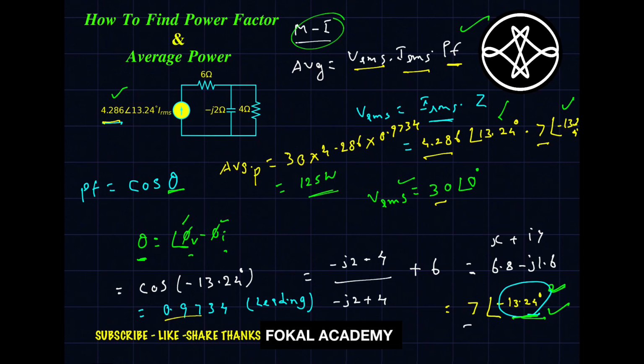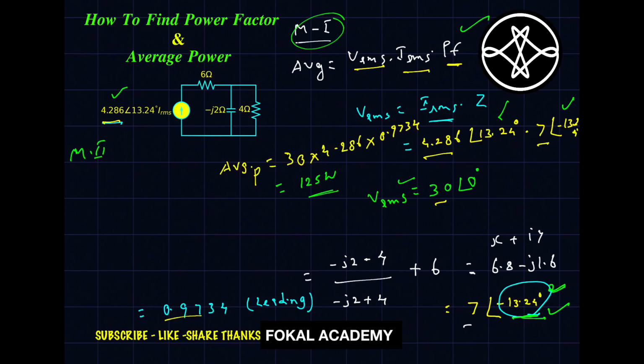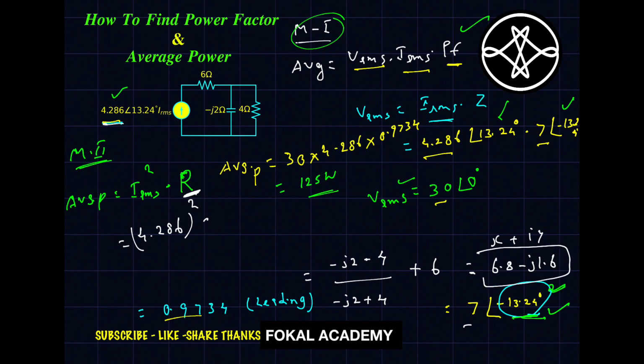Next, method 2. The second method for finding average power: P equals Irms whole squared into resistance. Irms is 4.286, whole squared, into R. So what is the R value here? In the overall impedance, the real part is called resistance and the imaginary part is called reactance. So this pure resistance value is considered as R, that is 6.8. By simplifying this, we get 125 watts. So R is always the resistive part of Z.